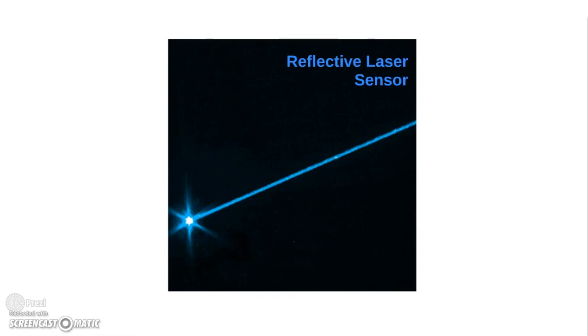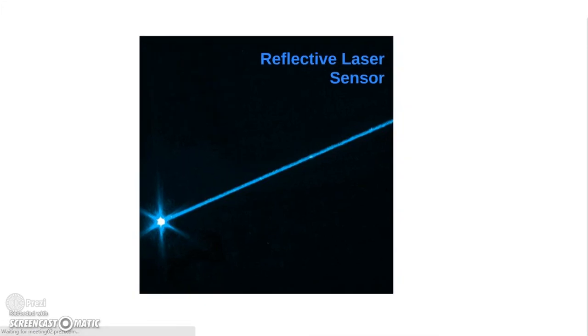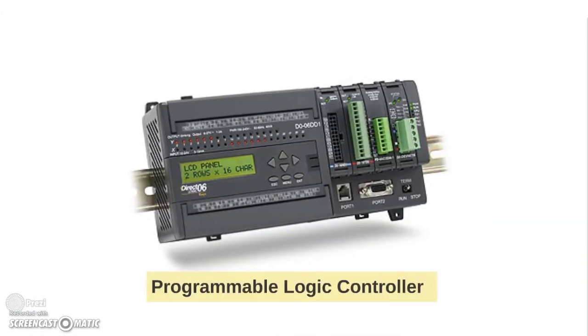The control system of the device is required to complete many functions, such as the analog to digital conversion of sensor data and the provision of diagnostic output in case of error. A programmable logic controller (PLC) was chosen as opposed to a microcontroller based device due to its more suitable programming environment for field support personnel. For machine control, a cascade control loop structure comprising an outer PI speed control loop and an inner PI current control loop was installed. Cascade control allowed the system to be more responsive to disturbances.